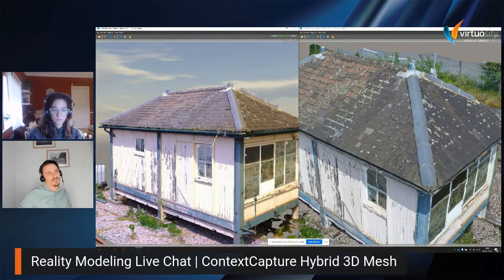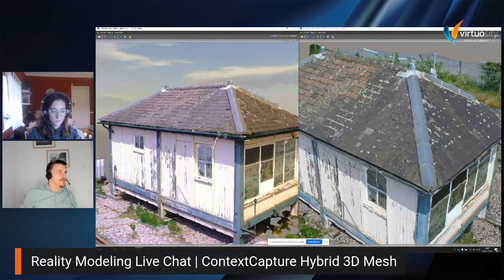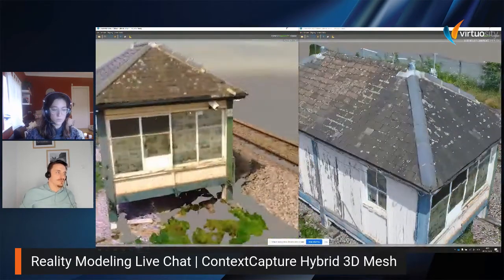We know already that the point cloud is going to be the most important thing, as this is a direct measurement. We are sending an infrared laser, which measures a point cloud, millions of points on each station. So we get a kind of discrete mathematical representation of the object in the world. Nice, that's great. But as soon as laser scanners came with a camera built in, and the camera after scanning took some pictures, then we can also add color to the same laser beam. Then we came out with the color point cloud, like you can see here.